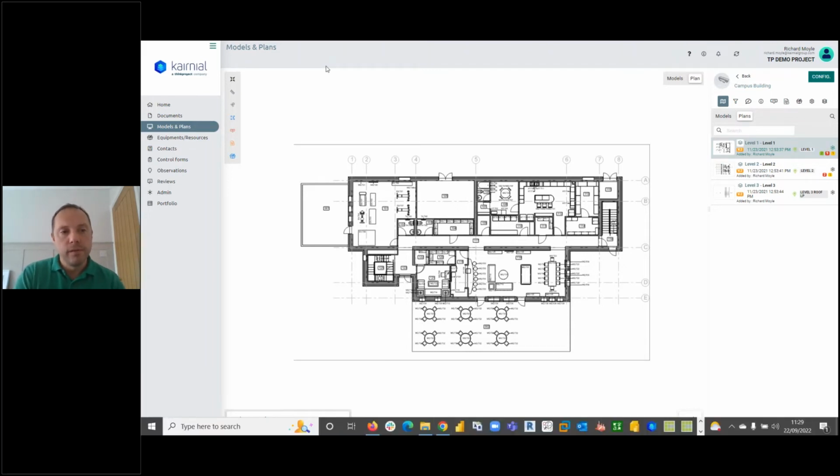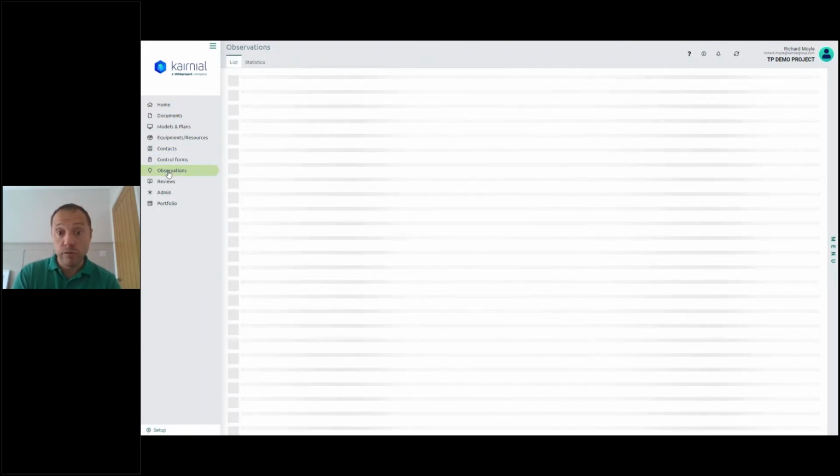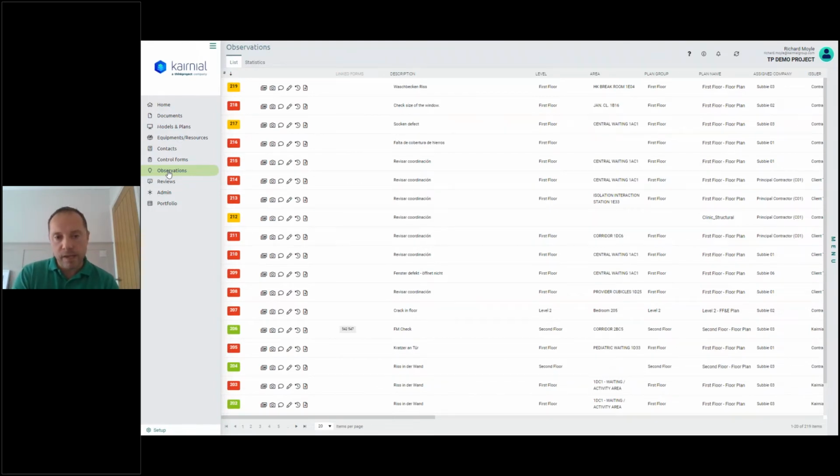From a processing perspective, you can have a register of all of the issues going on right now within that particular asset. Lots of our clients use our platform for sharing information, but the value of having the information in their hands is that we can start to manage the handover-related processes using that data, processes like defect management. Although the contractor does their own snagging and defect management, lots of our asset owners do their own defect management as well at the end of construction, because they want to ensure that the asset meets the quality and compliance level they're expecting.